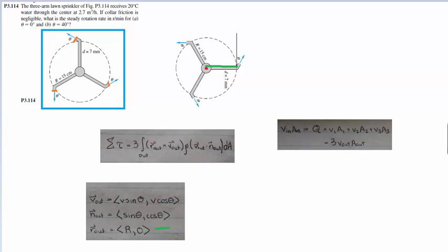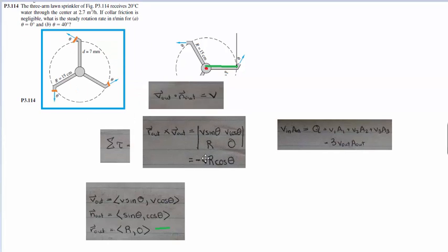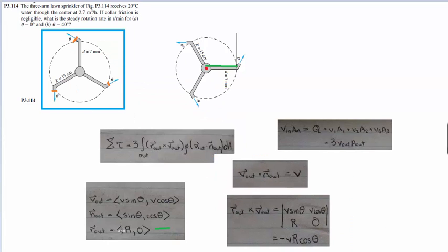So now that we have those, we just simply throw that straight into our vector equation, and our dot and cross product will come out to be this. So this time, our R out, V out. Well, remember when you're evaluating these determinants, first you go diagonally like this. That'll get us 0. And then you add that to this. But remember when you're going back this way, this is going to be negative, and this is going to be positive. So you get R V cos theta, and you get a negative sign coming out in front.